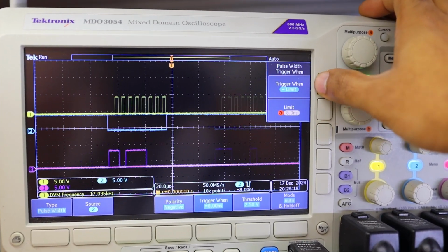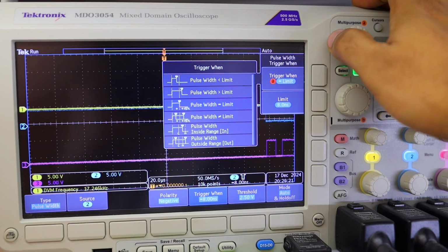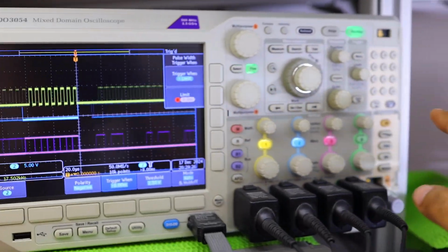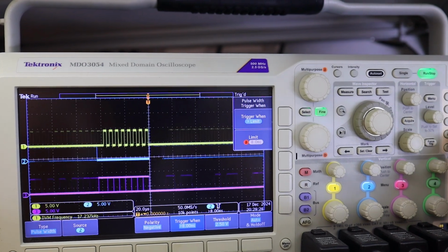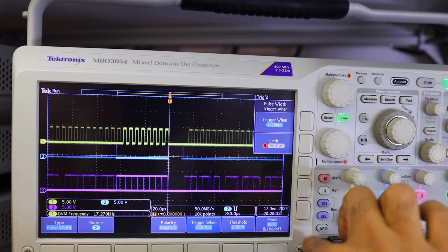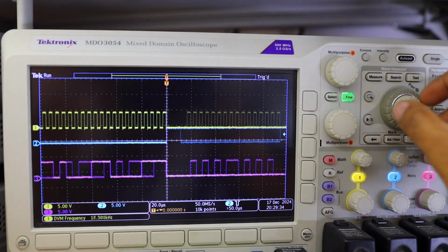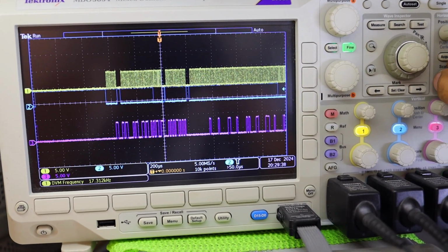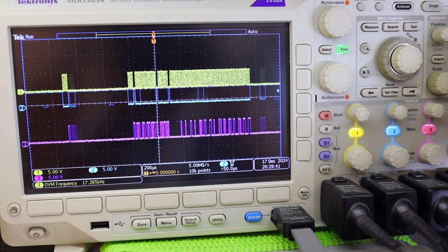If it does not have a tolerance, hitting an 8 nanosecond pulse exactly is going to be a challenging thing. Okay, and this oscilloscope has a really nice keypad, so you can just enter the value. Remember, last time we entered greater than 50 microseconds. This is an intuitive interface, and it looks really nice. Somehow we still do not see a stable trigger.